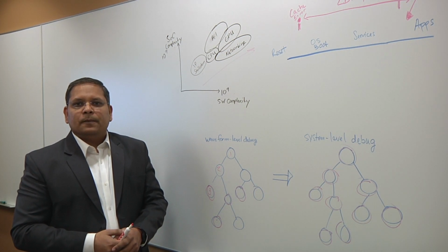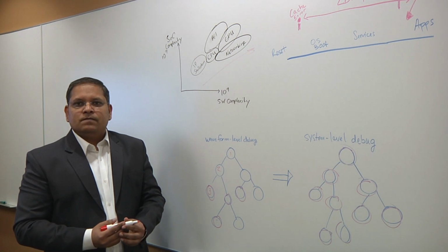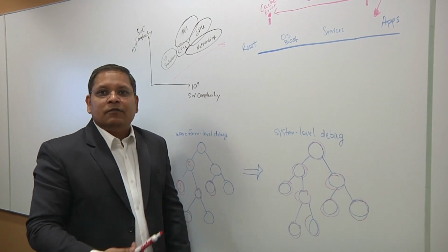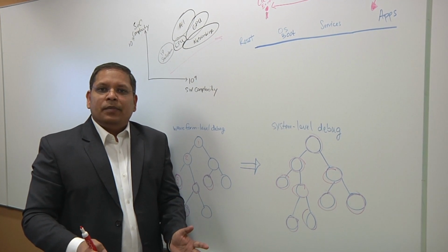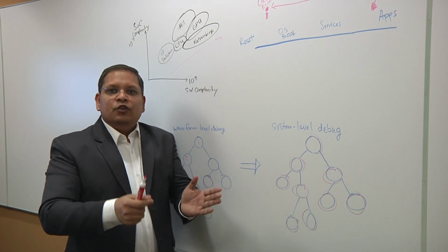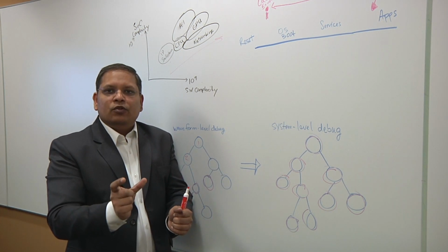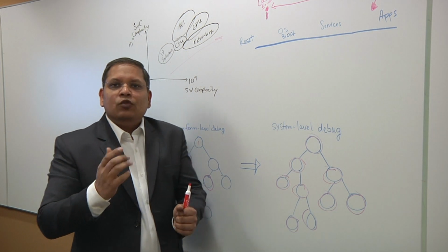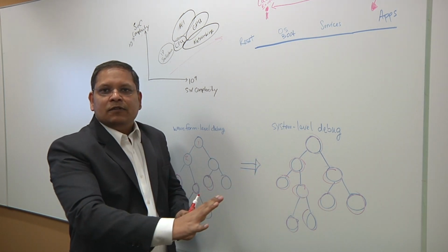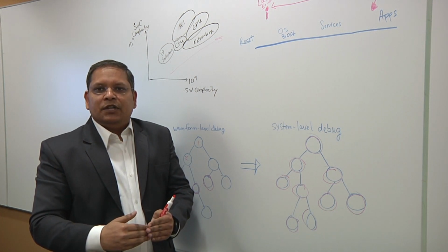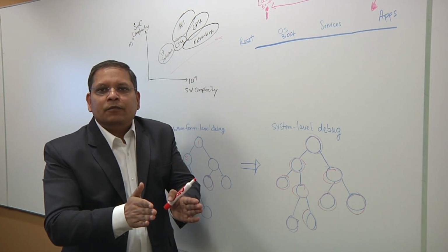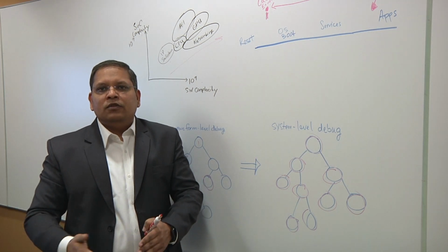And so what you're trying to do is collect more data, but also be able to make sense of that data too, right? Right. So this is where system level debug becomes a very powerful tool. We are collecting a lot of data, but then through the trackers, monitors, and checkers, we are trying to create a funnel and using that come to a point or find a window where the failure happens. So essentially, you only need 2 iterations to debug a problem. First one, where you've generated the entire system level information. You went offline, you analyzed the information, found the window, and then through deterministic bug reproduction, went into that window, did the waveform capture, and through native integration of your debugger tools, found the root cause.